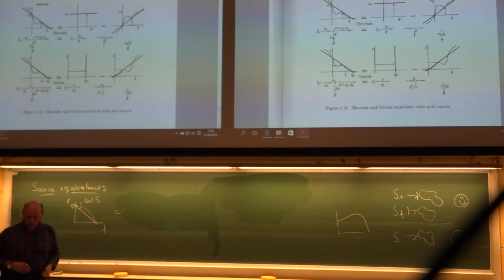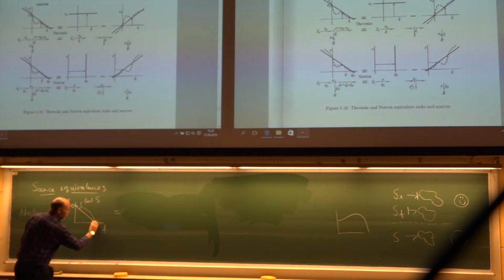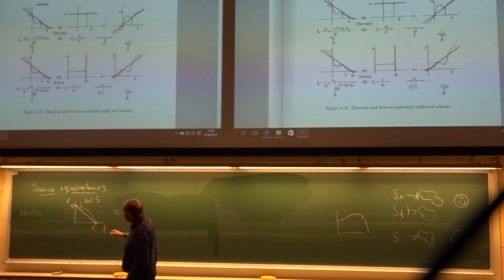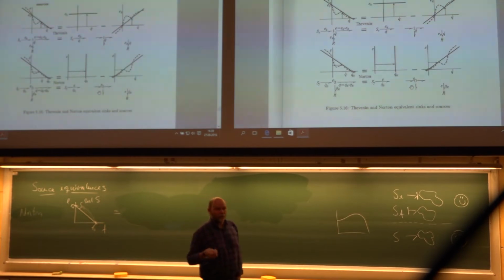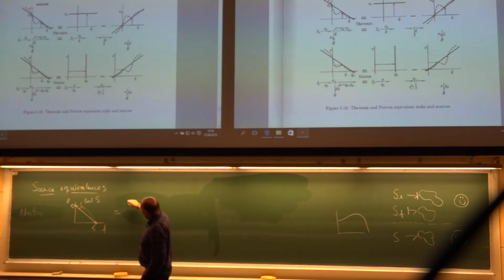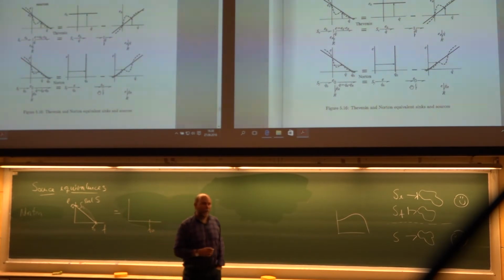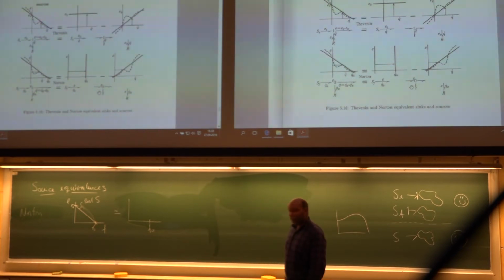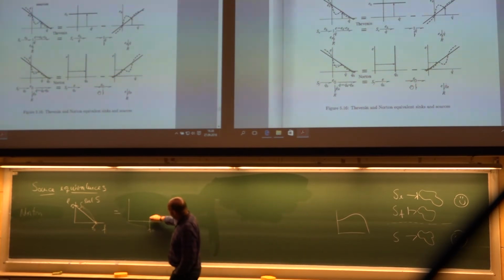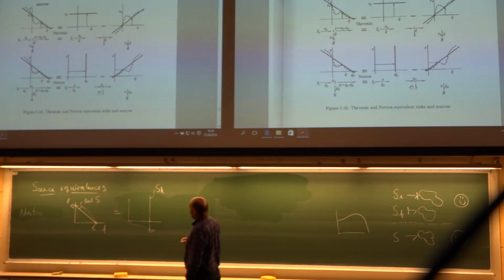So you have the same problem, but now we are focusing on this point, F0 or Q dot 0 if you like. So I want to obtain this, start with a linear behavior with a flow source, an ideal flow source. And for an ideal flow source, well, it will provide that flow regardless of how heavy it is. So it will just look something like this. Here you have an ideal flow source.